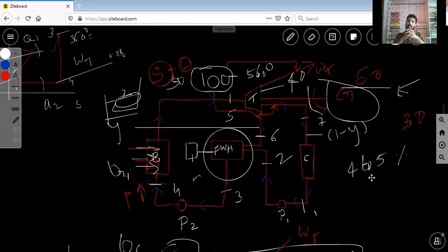What is the function of the feed water heater? Steam is extracted, or bled, from the steam turbine. That steam could have produced more work by expanding further in the turbine, but it is used instead to heat the feed water.